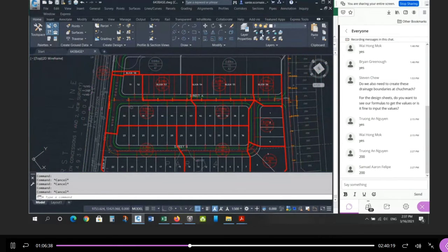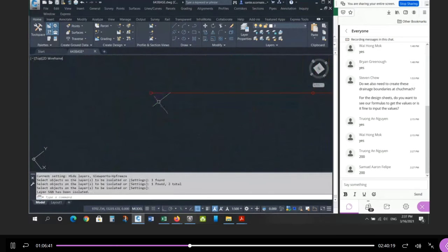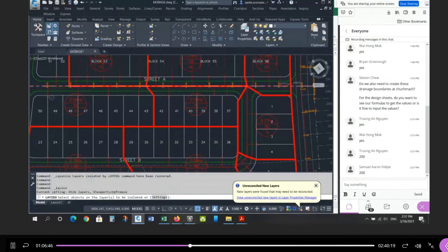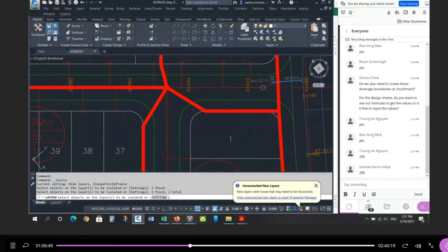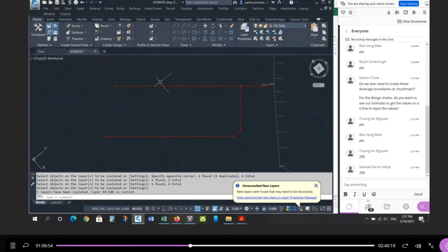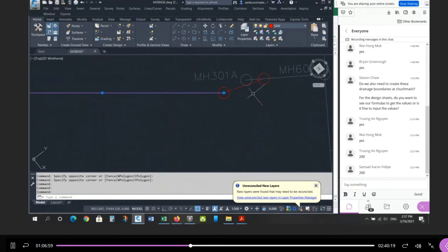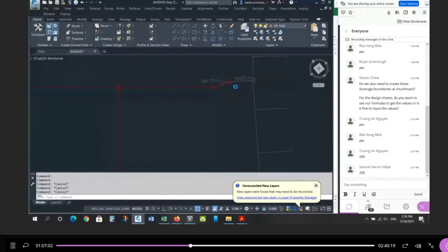Okay, and according to the maintenance holes, there are at least this many pipes, right, including the existing. You want to check the last pipe. Okay, so this is the system you're designing. So you have 1, 2, 3, 4, 5, 6, 7. You should have maybe 8 pipes proposed, and then I want you to actually show the first existing sewer to show that that pipe that's already in the ground has the capacity to take what we're proposing inside. Okay, so you have to show this on your spreadsheet.